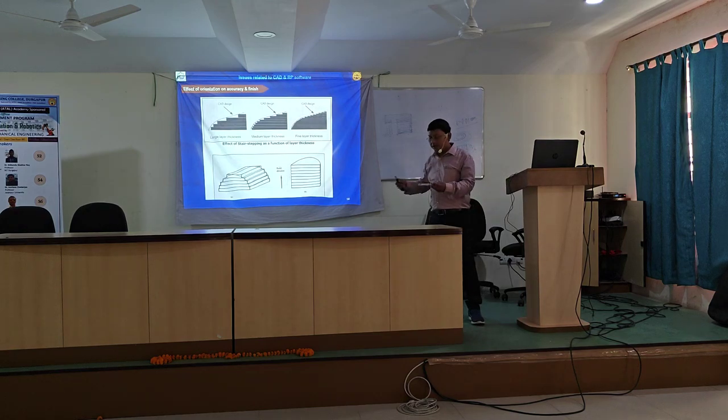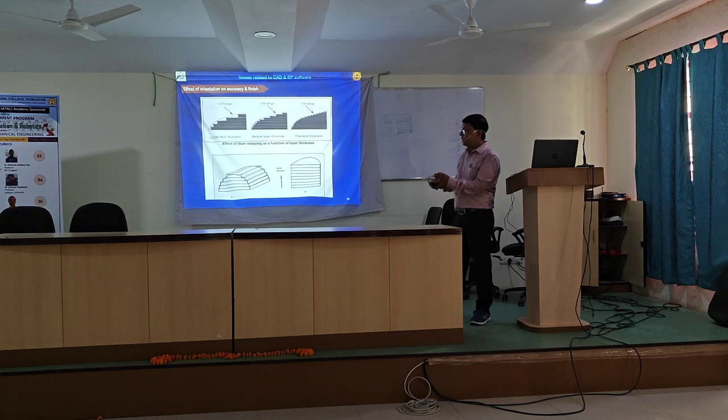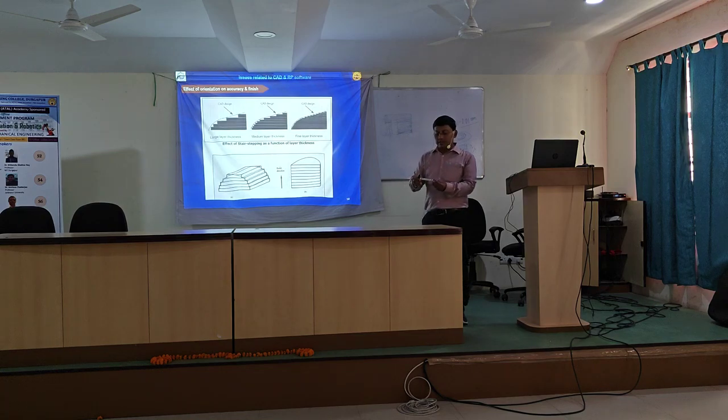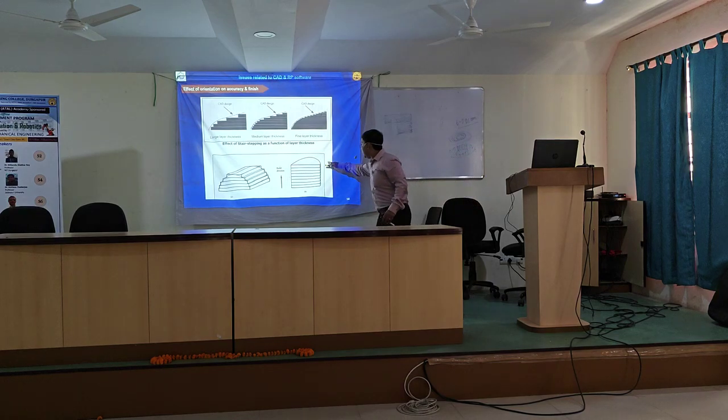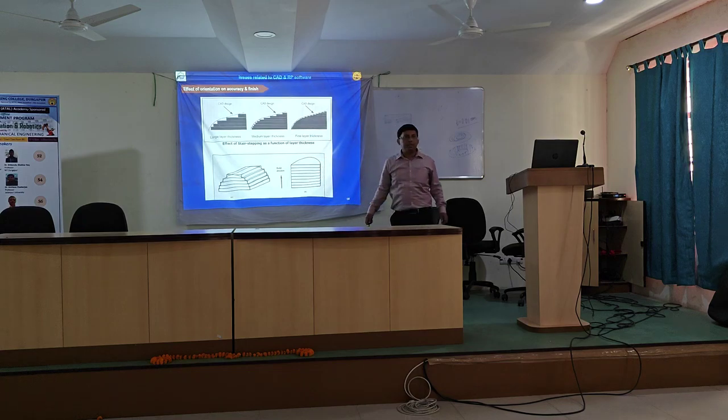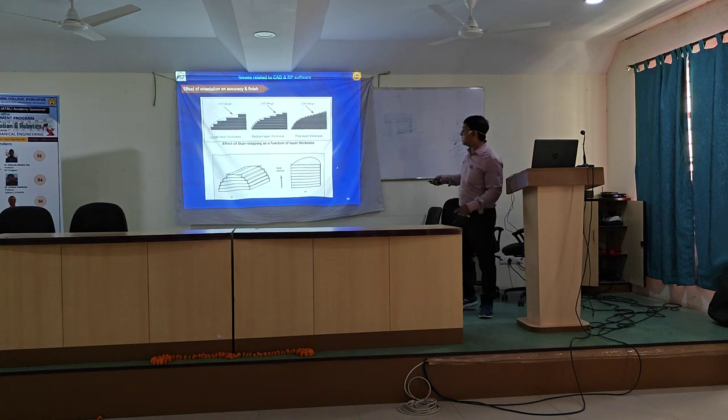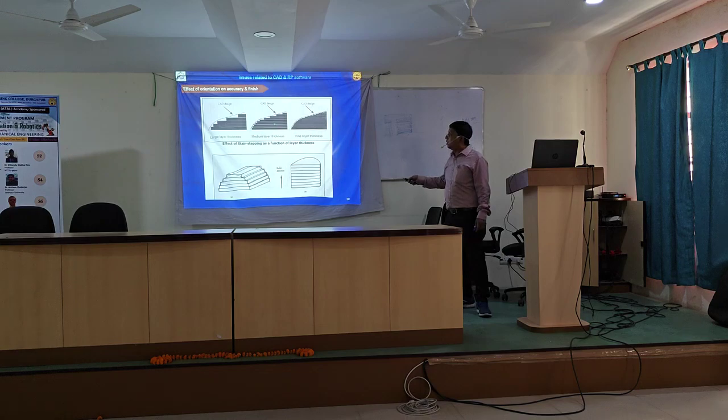Width is varied because it is a curved shape. See, curved shape. And because of that, when you deposit the material, this curved portion there is a stair step effect. But if you orient your object not horizontally, but vertically, then you do the slicing, each cross section will be a semicircle of the same diameter. That means there is no variation of the diameter, and as there is no variation of the diameter, there will be no such stair stepping effect.